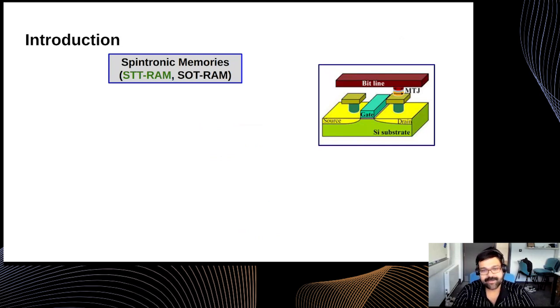On the right-hand side of the slide, you can see a small window where the MTJ is shown. MTJ stands for magnetic tunnel junction. We are mostly focusing on spintronic memory. The MTJ is the basis, the construction pillar, for these spintronic memories, and MTJs are attached to a substrate or transistors to work upon. Mostly the circuitry is prepared with one transistor along with one MTJ to store one bit in the memory.